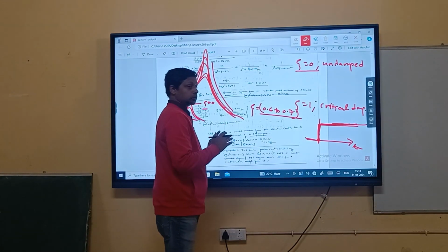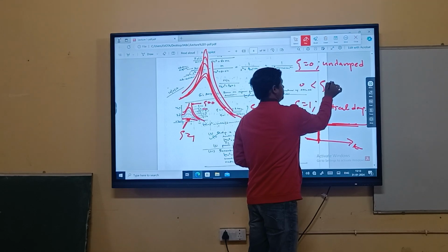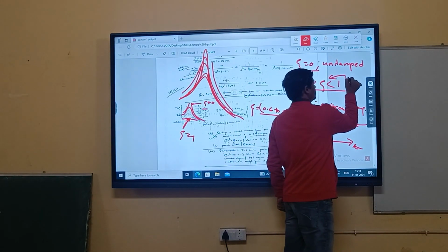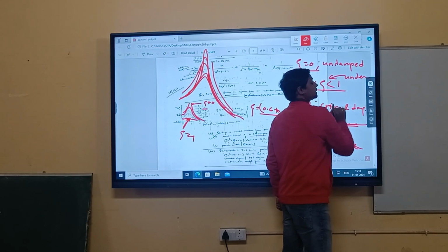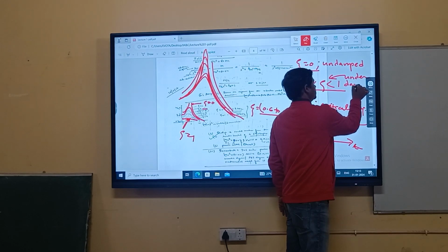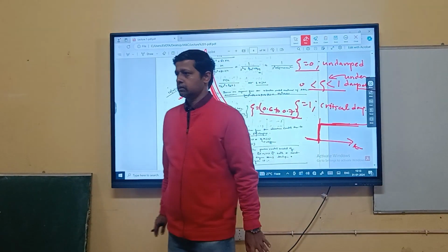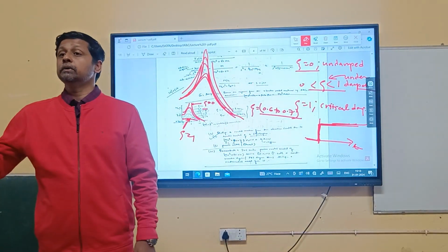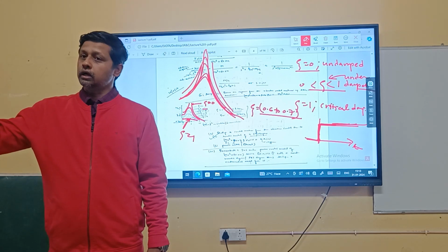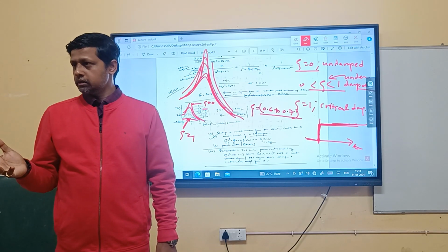Why? Because it also needs some time. Because now you are allowing the damping purposely. Why are you allowing it? Because you want to deliberately achieve this underdamped condition. Under the underdamped condition, you want your system to experience some damping. Why? Because ultimately my desire is that this system should settle down. Are you getting my point?